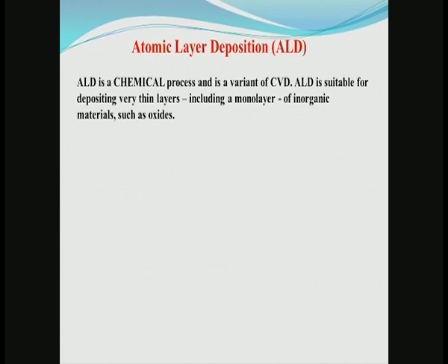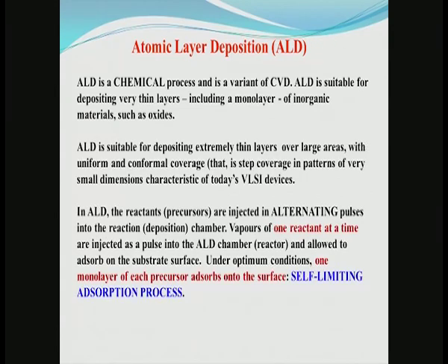ALD is a chemical process and is a variant of CVD actually, because chemical reactions are involved, and ALD, as I said, is suitable for depositing very thin layers, including a monolayer of inorganic materials such as oxides. ALD is suitable for depositing extremely thin layers over large areas. So, one advantage is that it is capable of producing very thin uniform layers on substrates as large as 300 millimeters, which is today used in VLSI manufacture.